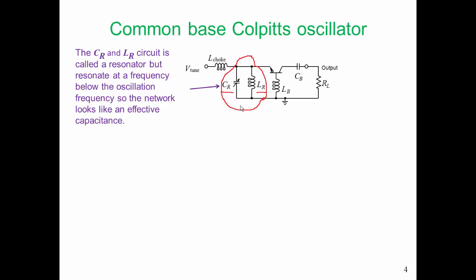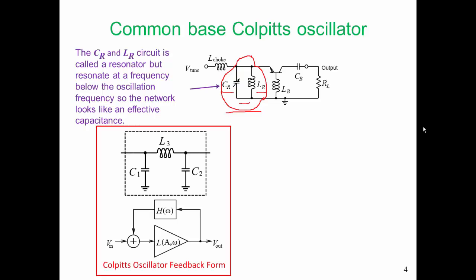And the key characteristic that we achieve by using this resonator structure is that the susceptance of that effective capacitance has a slope with respect to frequency that we can control. So it's a very nice idea, this idea that we don't just put a capacitance there, we put an element in there with which we can control both the susceptance and the slope of the susceptance. Now I'd like to show you how this relates to a traditional Colpitts oscillator.